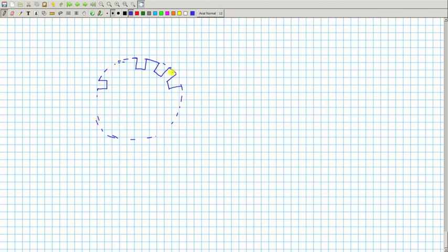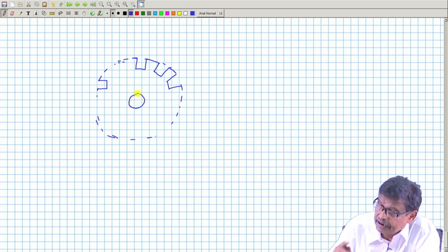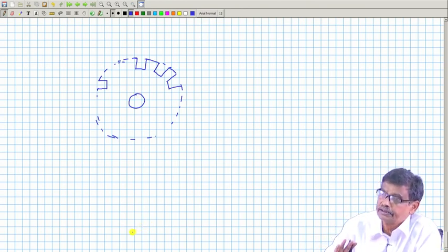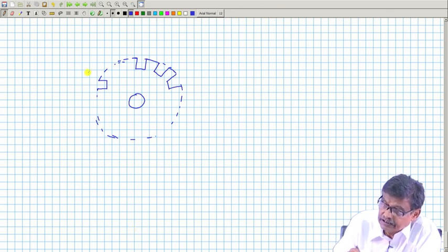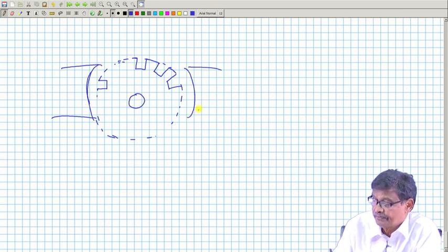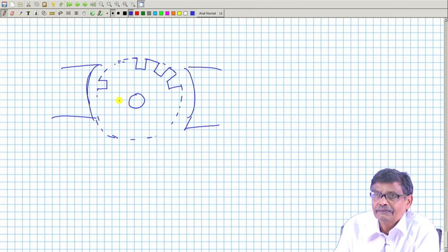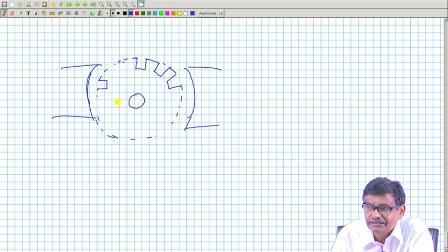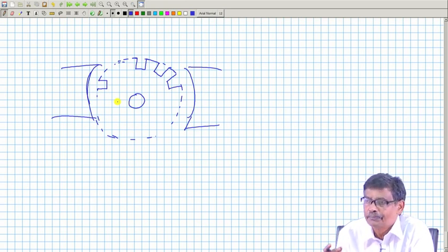This is one plate and its thickness is few millimeters, and then you give a varnish coating to this plate and then stack many plates one above the other, and you will get the height that becomes the length of the machine, and this fellow will be rotating in your steady field. Field is steady. Therefore, eddy current loss will take place, but this time it will be less. Why? Just like transformer, you have reduced the path of the eddy path.